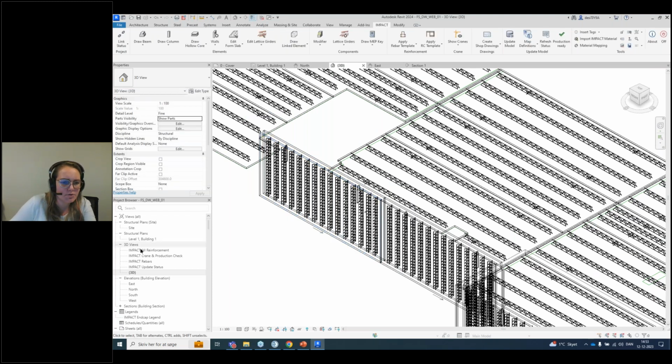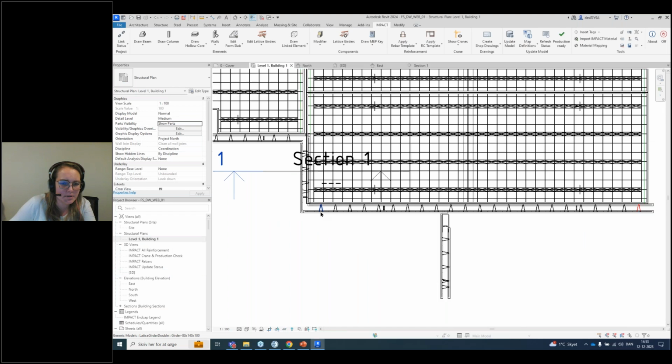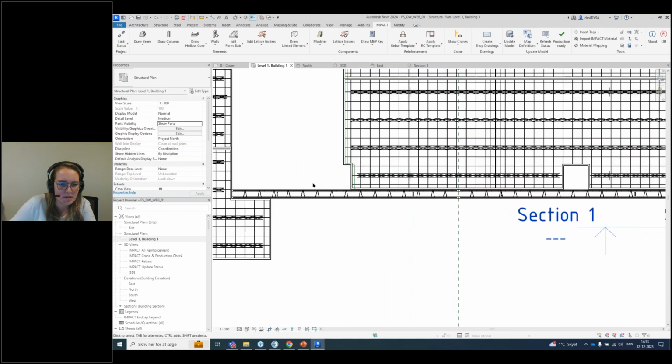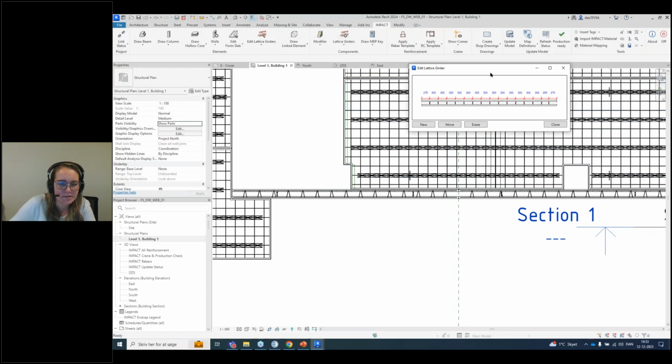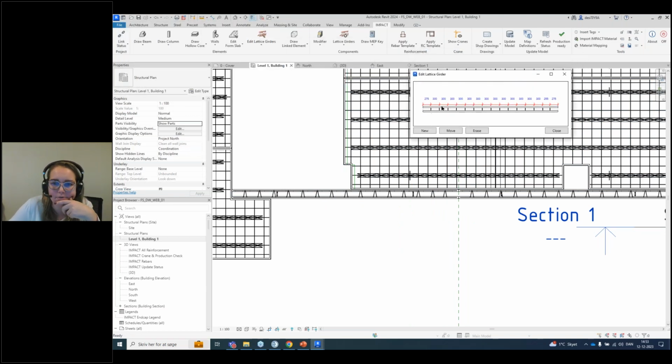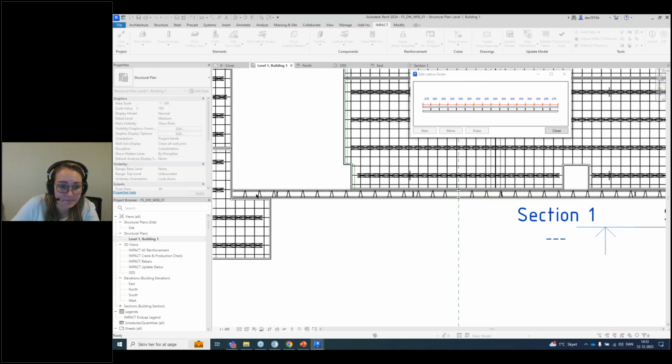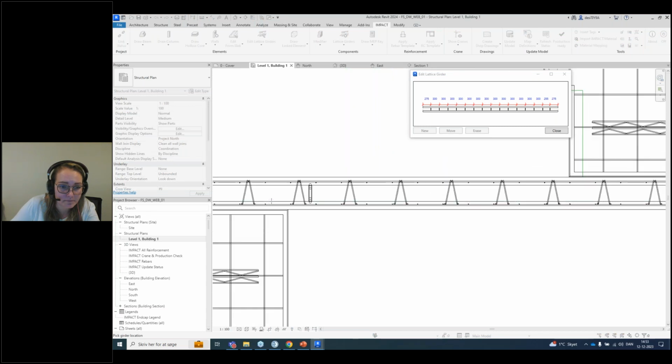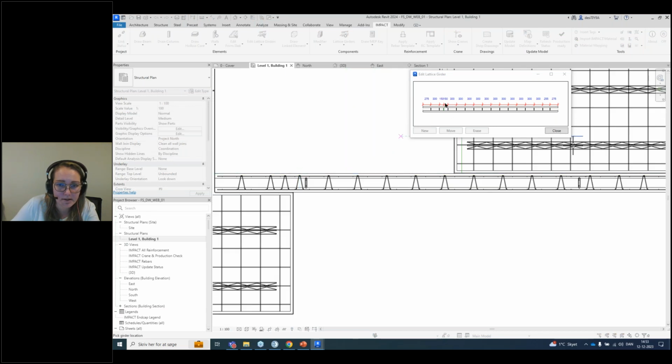Now, I want to show this on the plan level because that's easier to follow. So let's take this wall in here. If you want to edit a lattice girder, we have this functionality where you can actually see the distance between the girders, and you can draw a new one. You can just draw one here, right?